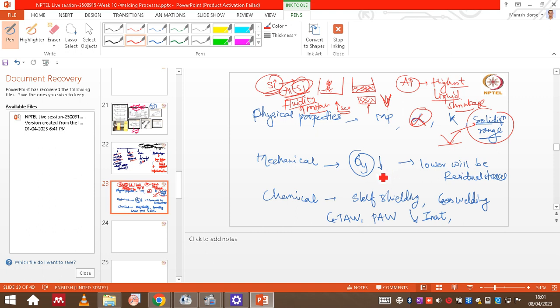And also if the material surfaces are not that active. Let's say if we consider aluminum and titanium alloy, the materials are very active and susceptible to oxide formation. So for those materials or processes, again we need extra shielding. Okay. So if the material is not active and has certain kinds of physical properties, then it is good for fusion welding processes.